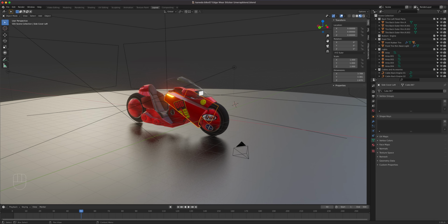Okay, but to summarize again: collection or outliner, property window, sidebar, toolbar, menu bar, workspaces, tool settings. Tool settings, like if you have a brush, you'll see the radius and strength here in the tool settings. And the last one right here will be your timeline. Okay, so that basically sums up the Blender interface.